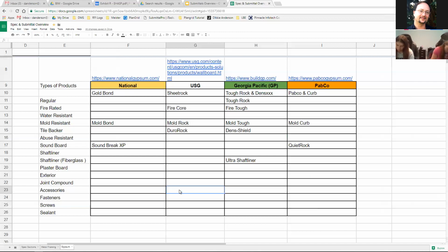And we use steel pins for structural framing, and we use concrete pins when we're attaching to concrete. We use both those pin sets for the Division 5 structural framing and Division 9. So when you do your submittal, you just copy and paste the same thing because we use the same type of power actuated fasteners for both those divisions.